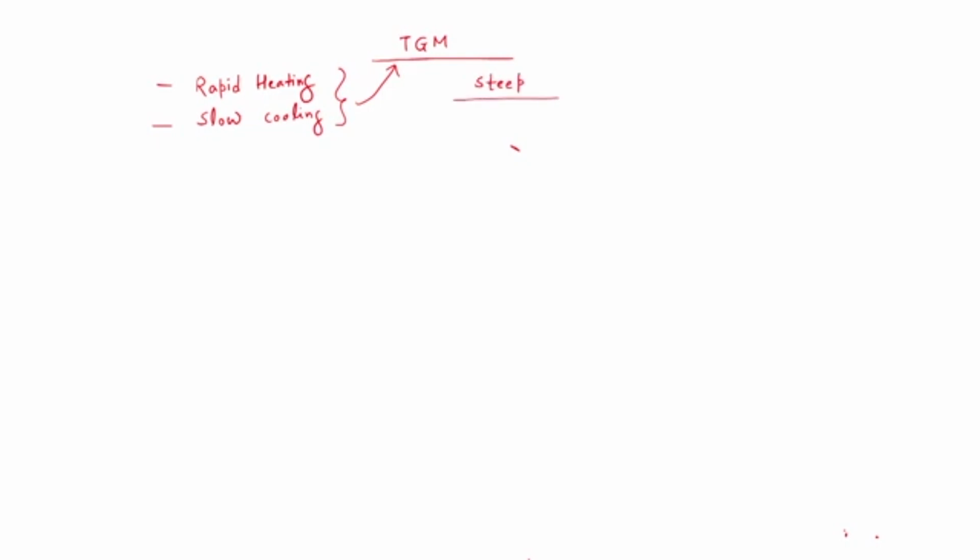So, to get this steep temperature gradient, the laser must travel at a speed which will generate thermal diffusion depth less than the thickness of the worksheet.